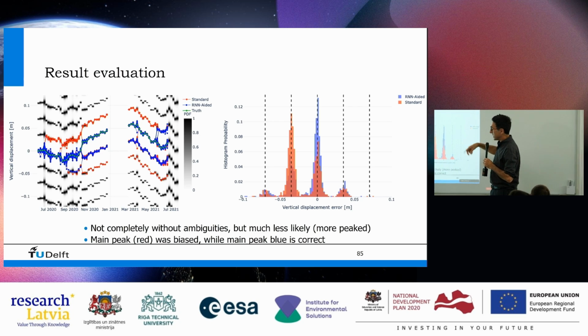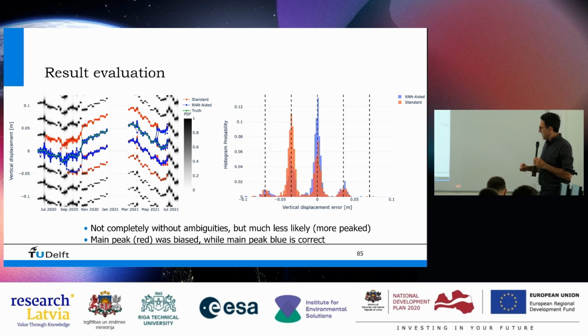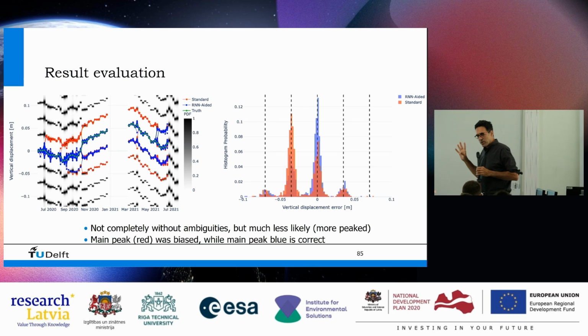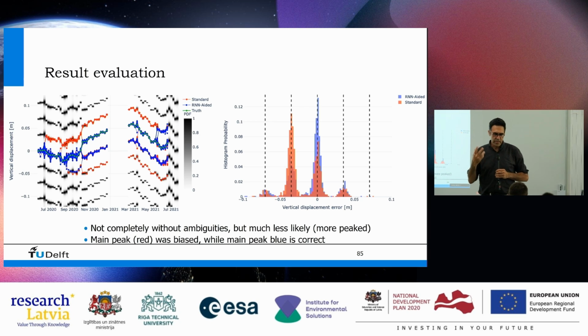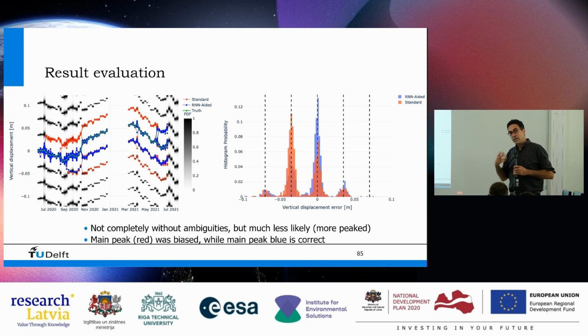And with our recurrent neural network using precipitation and temperature, so contextual data, most of our solutions are actually in the right direction. So the point that I'm trying to make here is that phase unwrapping, estimating the ambiguities, is something that is very complicated. There is no true solution. Sometimes if the signal is so dynamic, it's almost impossible. But the trick to try to improve is to use information from the outside, information from precipitation, rainfall, maybe land use, that could help in finding a better solution.